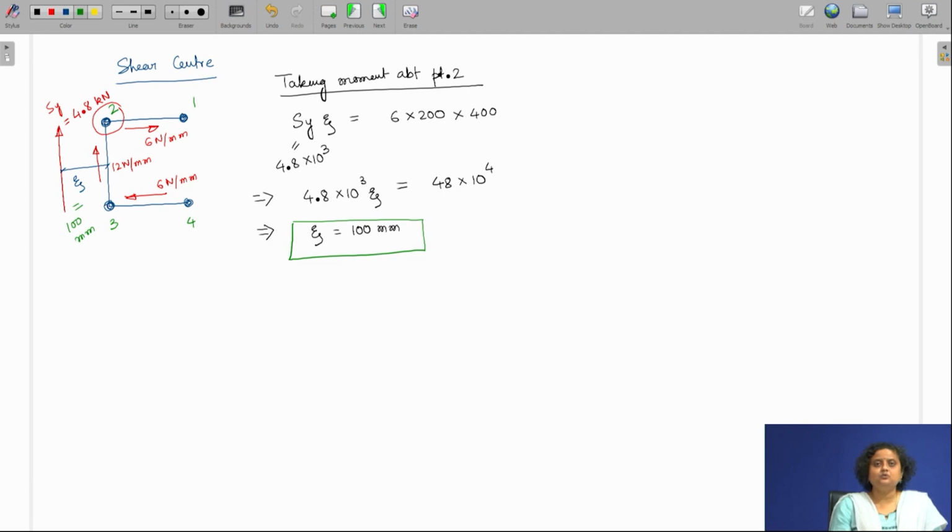But when we do skin stringer idealization, the problem is simplified to a great extent and therefore can give us quick solutions. Next, let us solve. We have solved an example on an open cross section beam. Let us solve the example of a closed cross section and see how we can find the shear flow there.